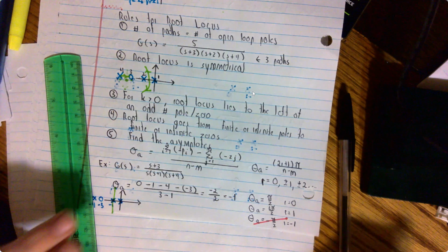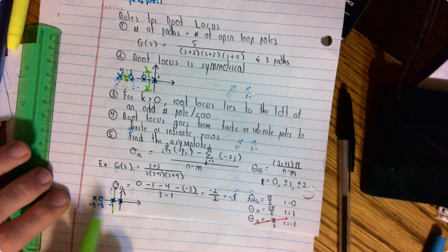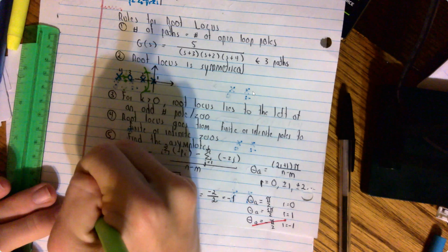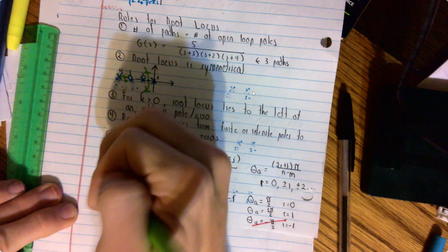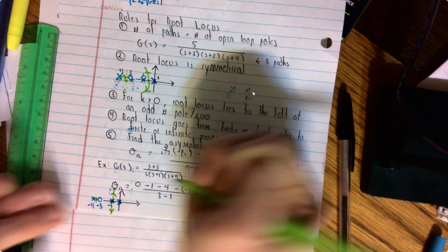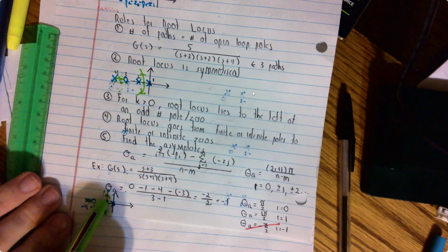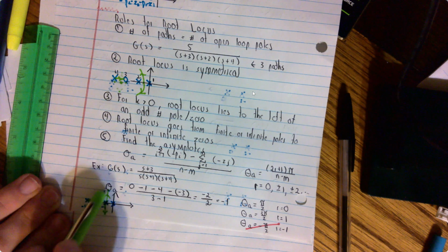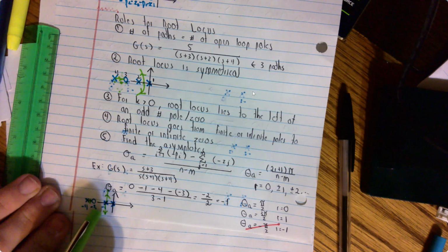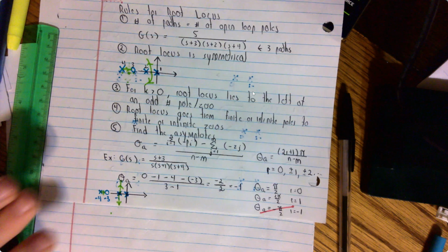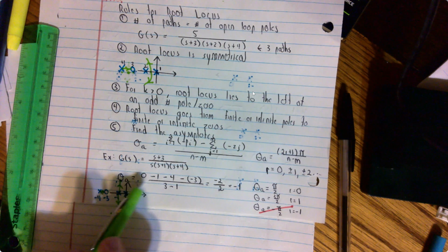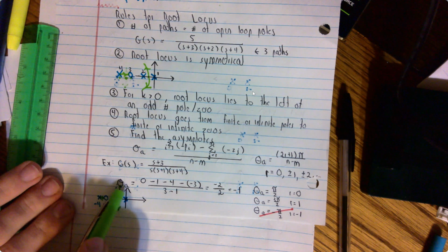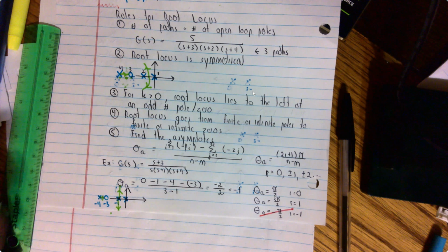So if we look at the path, this pole is going to go to this 0, right? Because 1, 2, 3, 4, there exists a path right here. And then these two, they're going to go up in this direction. Basically, it's telling you one's going to go up with an angle pi over 2 from the real axis. The other is going to go with an angle of 3 pi over 2 on the real axis, so one's going to go downwards. And so our asymptote is at -1, and so that's where the center asymptote is, and it has an angle pi over 2 and -3 pi over 2.